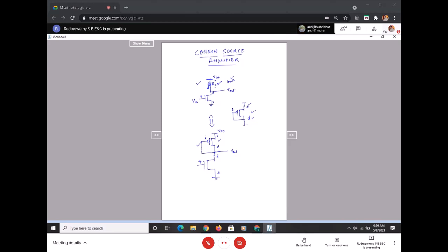The moment I make this particular transistor operate in saturation, and we know the IV characteristics, right? The output characteristics, yes, the moment the transistor is operated in the saturation region, its current is constant. So that's why ensure that the PMOS, which is sitting on top of the NMOS, this is my NMOS, operates in the saturation region.